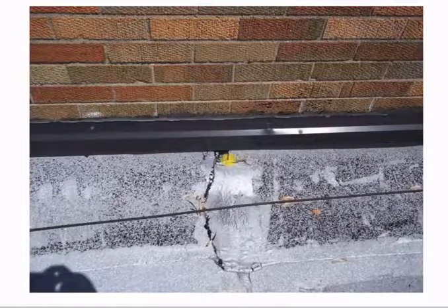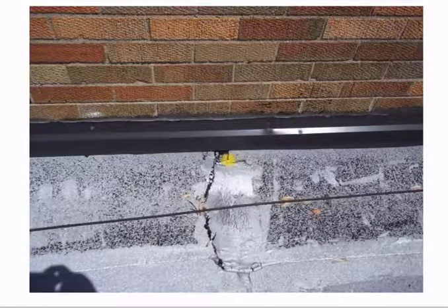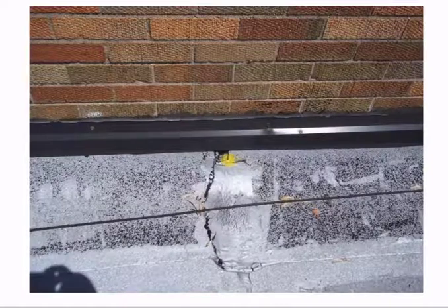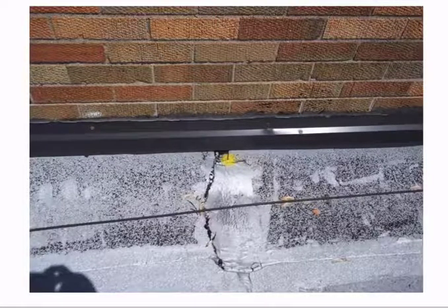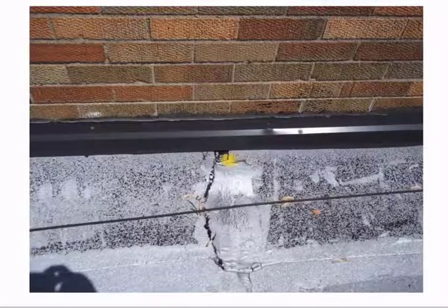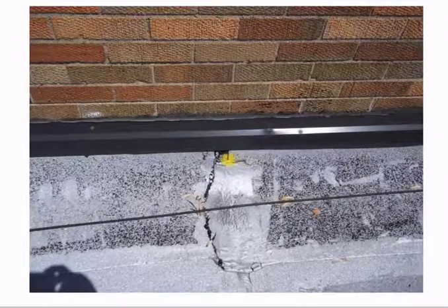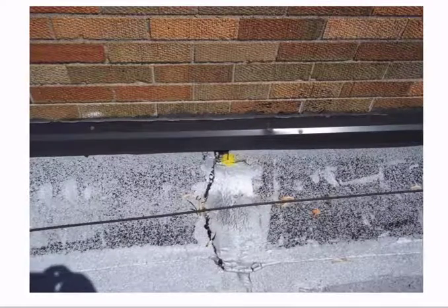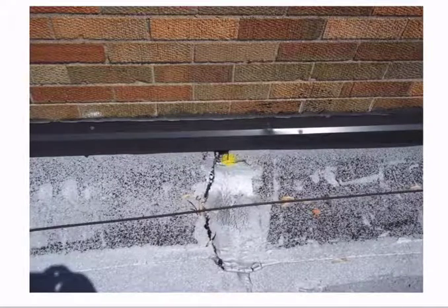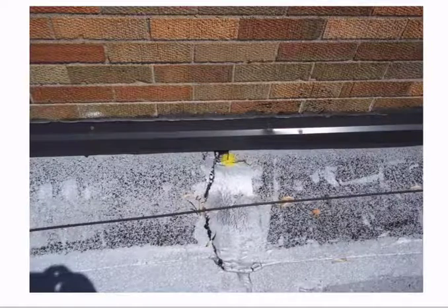Again, base flashing deficiencies, a clear failure of the system here, that's going to create a leak. Typically, what would we see done here, and what should be done? This would be a repair, but it looks like the cause is someone used some winter grade mastic, and maybe not enough cutback primer before they applied the mastic. The typical contractor would probably just put some roofing cement at the top of that flashing and walk away.